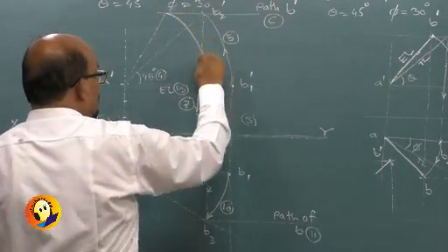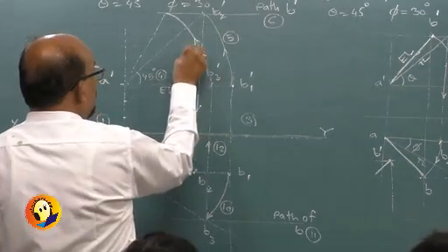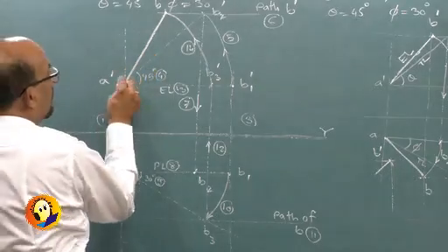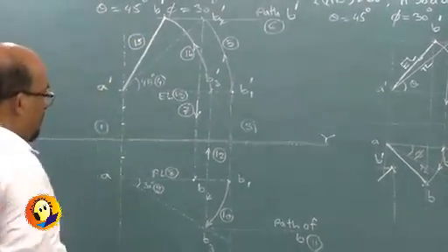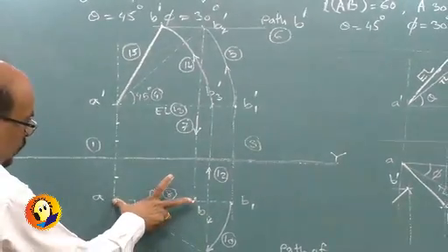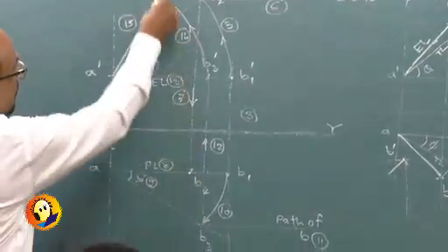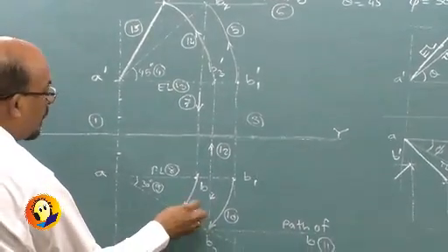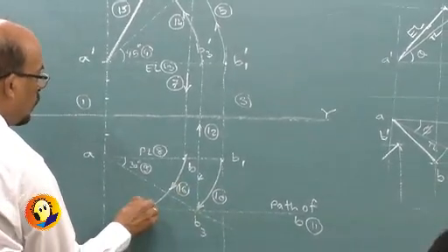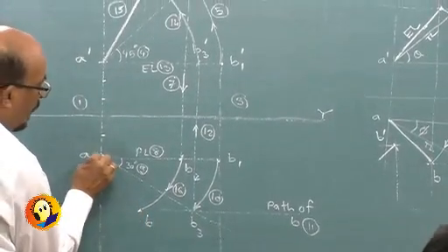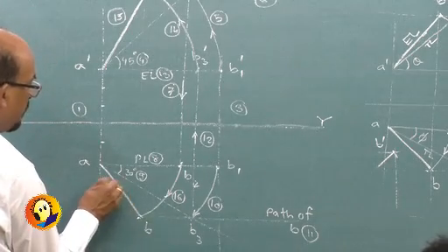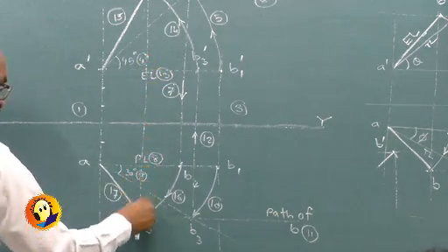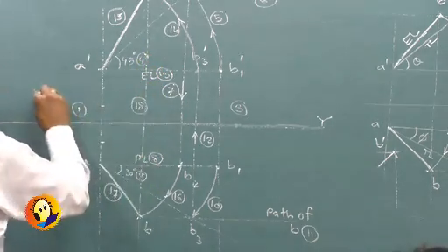So elevation length is rotated is step 14 to get point B dash, step 15, and rotate plan length is step 16 to get point B, and plan length step 17, and finally to check whether they lie on the same projector or not is step number 18. Job is done.